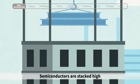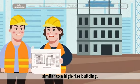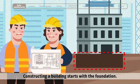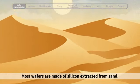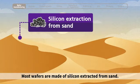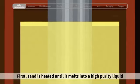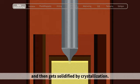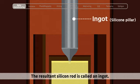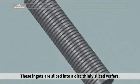Semiconductors are stacked high and solid to form a complex structure similar to a high-rise building. Constructing a building starts with the foundation. A wafer is the foundation for the semiconductor. Most wafers are made of silicon extracted from sand. How can these tiny grains of sand become a wafer? First, sand is heated until it melts into a high-purity liquid and then gets solidified by crystallization. The resultant silicon rod is called an ingot. These ingots are sliced into thin disc-shaped wafers.